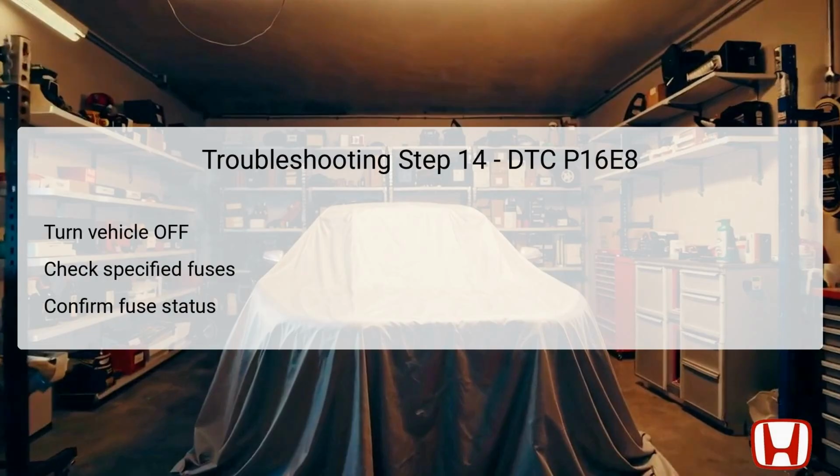If the technician confirms the fuses are intact, we progress to check for other potential faults in the LIN communication line. Conversely, if either fuse is found blown, it's critical to investigate wiring for shorts in their respective circuits, and replacement of the damaged fuses will be necessary. Understanding fuse integrity is crucial, as a blown fuse often serves as a primary indicator of further electrical issues needing resolution.